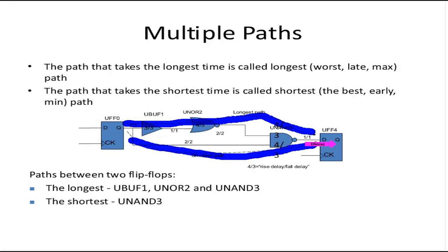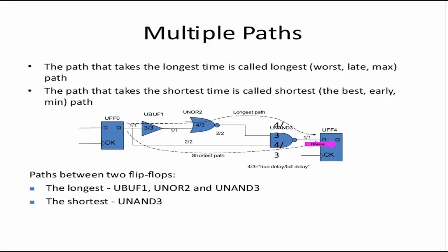Now in the last session, the last slide had one exercise where you had to calculate the setup and the hold slack, and in that I mentioned two values, the max value and the min value. This is one reason why every node will have a max value and a min value, because there are multiple paths through a number of cells.